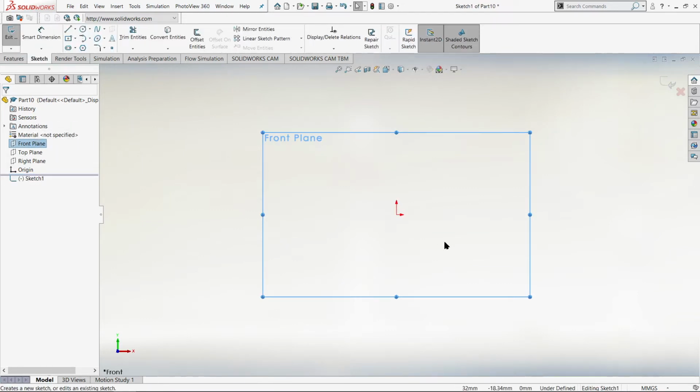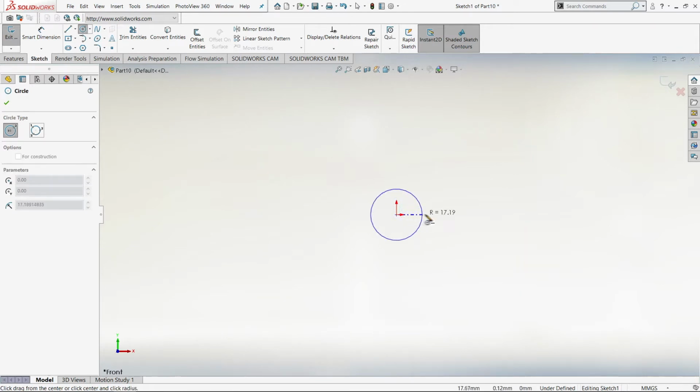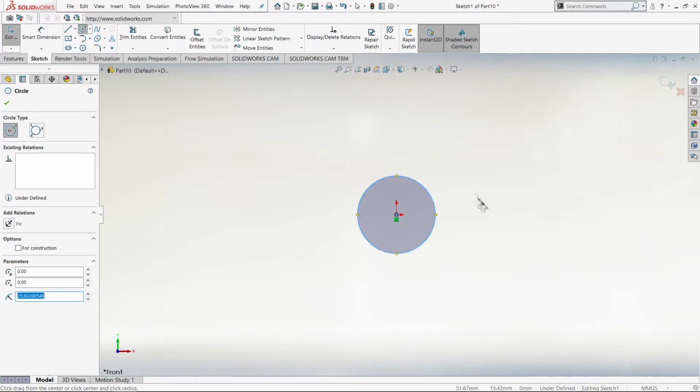Now in order to extrude a cylinder, we'll need to go ahead and draw the face, which is a circle. So let's go ahead and get the center circle tool out and then click on the origin as being our center point. Go ahead and drag out to roughly what we want. I roughly want a radius of 25, and then we can place that.